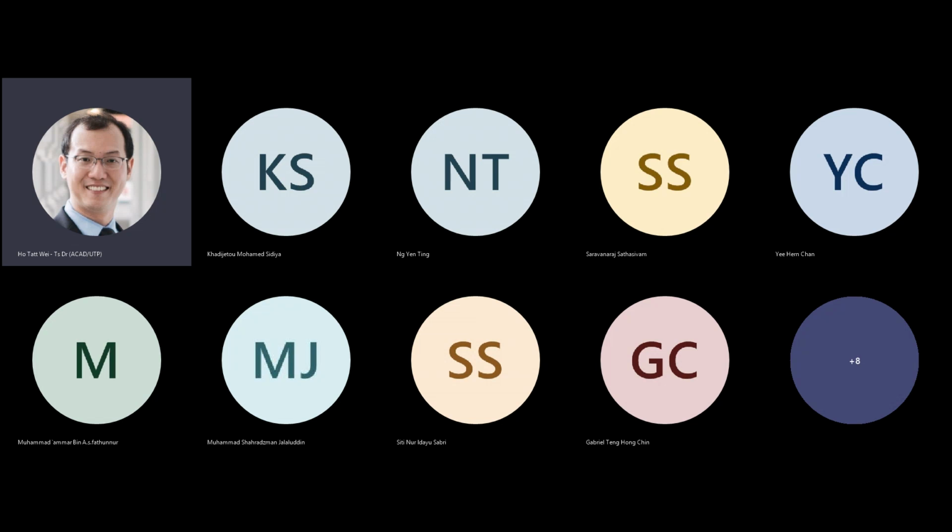And this is where you can see, back to that current equation, mu C ox W over 2L times VGS minus VTH squared, there is a temperature dependence here.